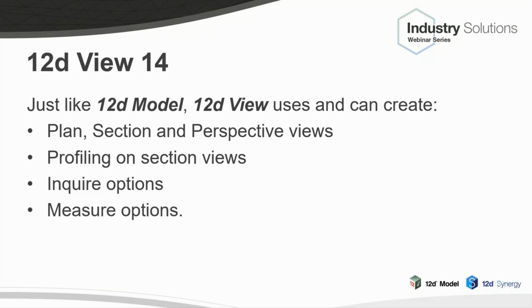And the measure options. So you can do chainage, offset, pick set values, look at attributes. Again, all those different ways you can do, and because it's full 12D model design data, there is no problem. You can get a chainage from alignment string. All that is available to you right there. You don't have to do weird things to get access to that data.